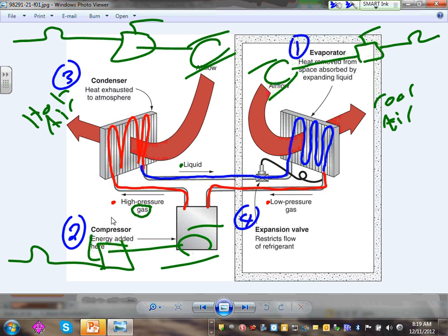So this evaporator will be inside the air handling unit. So you put an evaporator inside the air handling unit, you blow the air through the evaporator, which is carrying water. Then the water will collect the heat from the building. You pump the water through big fat pumps all the way to the chiller to chill the water. Chilling the water is removing the heat out of it, guys, right? Remove the heat out of the water and shoot the water back again through another pump all the way to the air handling unit, and you keep doing it over and over and over again.